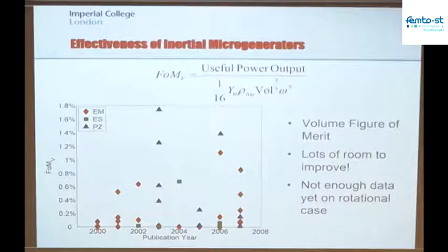When we're talking about these linear devices, we're talking about having typically a harmonic excitation at one frequency, and if it's a linear device, if it's the velocity damped resonant generator, then the mass inside the device is moving also sinusoidally because everything is linear. Actually, what you find is if you start to introduce some harmonic content into the forces that the mass is seeing, you're able to effectively take away the movement of the mass at the peak of its travel and then effectively increase the fundamental displacement a little bit more.